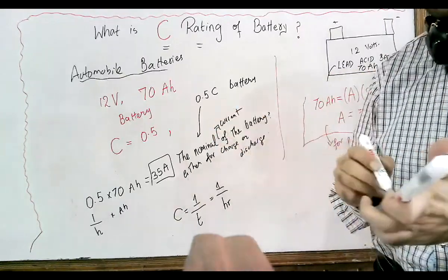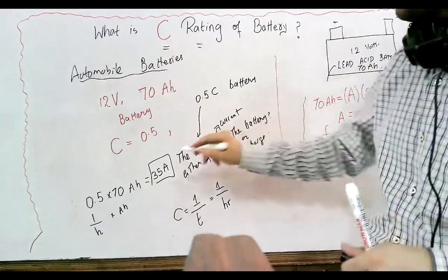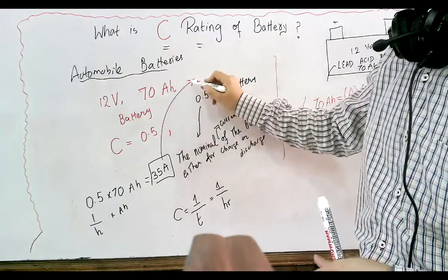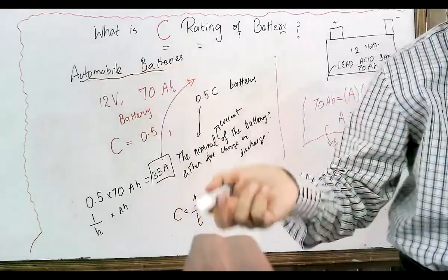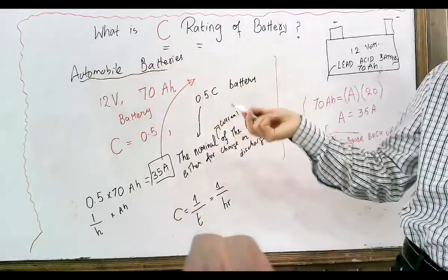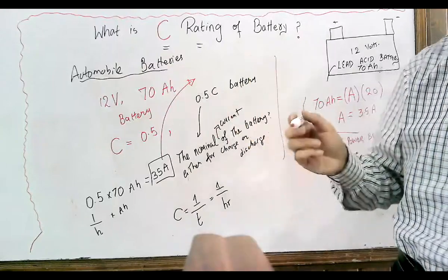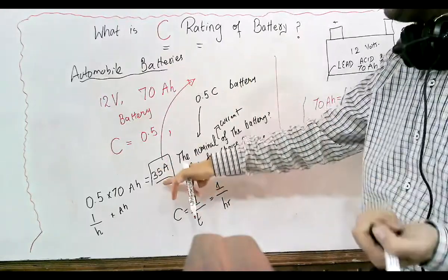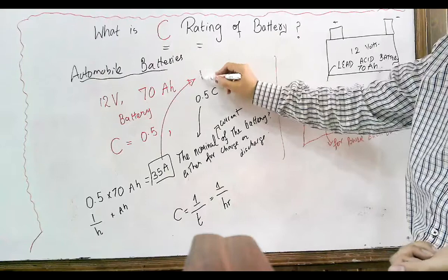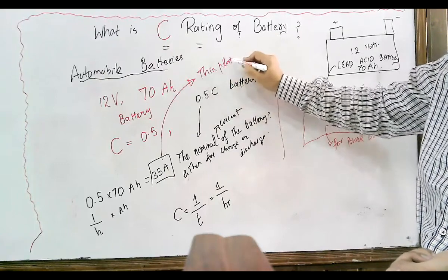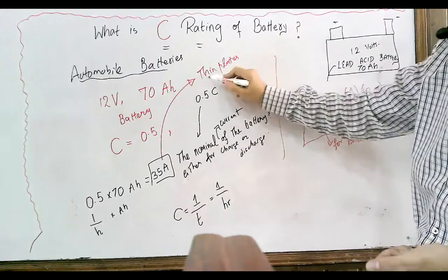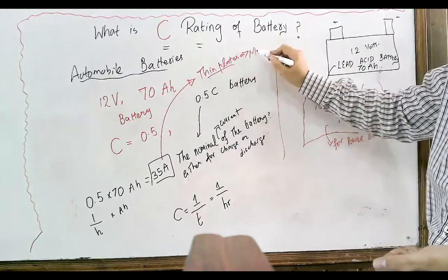It is somehow the battery which is more favorable for automobile batteries, or it is a more advanced battery if it is mentioned that it is used for solar. Normally, in order to increase the C rating, you have thin plates, and the plates are more in number.